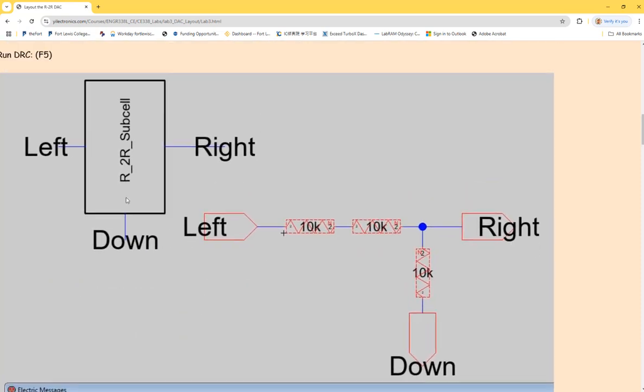After you create the icon view, the icon will directly show up in your schematic view, like this. So when you want to modify the icon view's labels, text size, font size, or anything else, where should you add those details of the icon? Directly in the schematic view or somewhere else? In the icon view, remember.